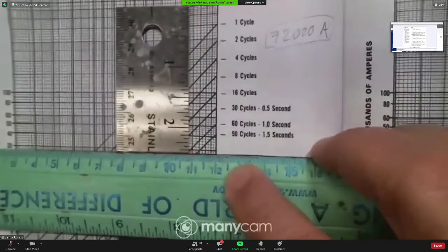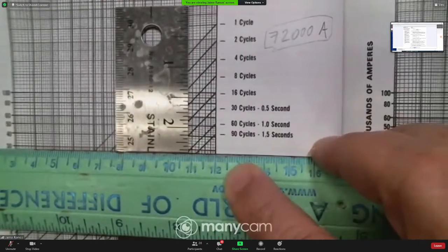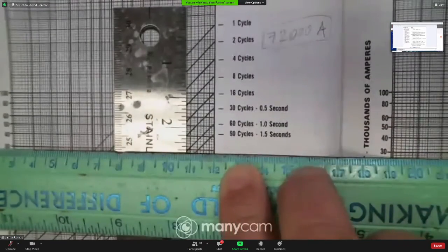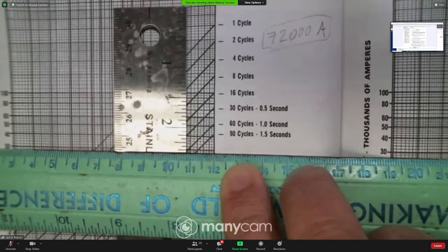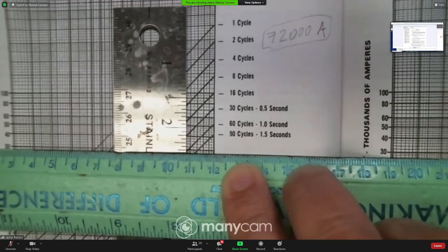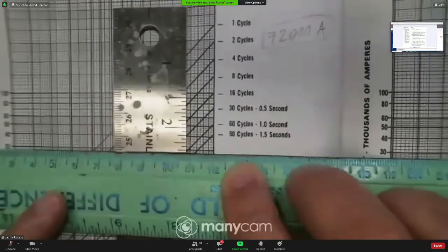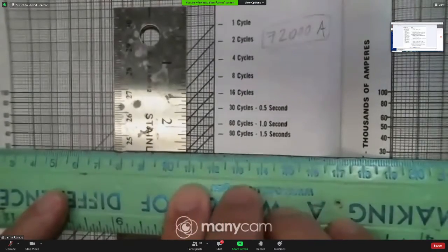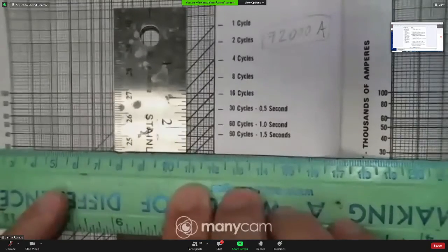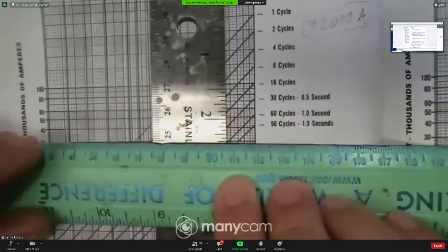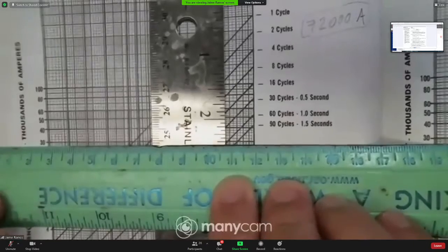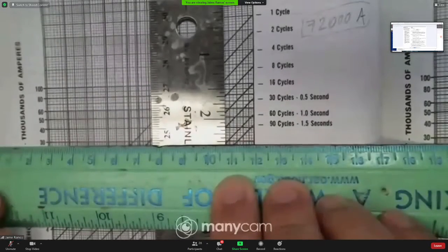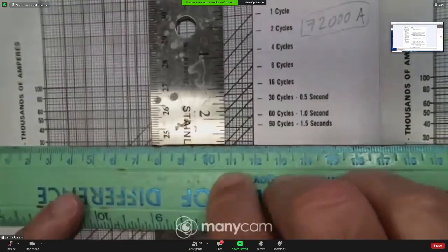So it'd be around 30,000 amps. Minimum size is number 1. So 1.0 is okay because it's good for 30,000 amps, and the asymmetric current is 22,000 amps.